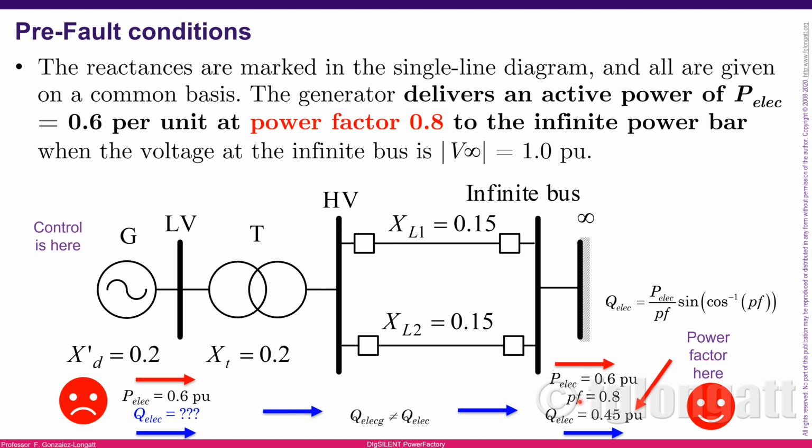If you disregard this important line, you will be in trouble, because basically what you are doing is ignoring the pre-fault conditions, the pre-contingency conditions, okay? And this is not the first time. I saw this in very important consultancies around the world: because they cannot do the full pre-contingency conditions, they start to run calculations with the system that they have.